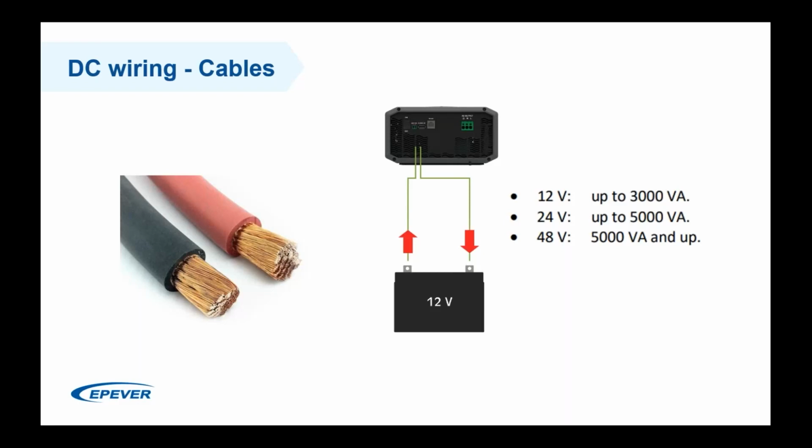Voltage drop happens when the current travels through the wires. If your wire is thin, it will have higher resistance, and then you will have higher voltage drops in your system, the efficiency of your system will be lower, and it will cause other problems such as thermal problems or heating. To find out the core diameter of a standard cable, we can look at the cable insulation. Normally there are markings on the cable that indicate the cable core thickness.